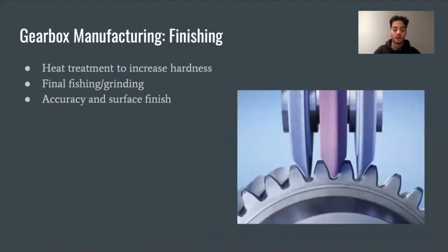After machining, gears usually require heat treatment in order to increase the hardness of the gear, and after heat treatment, gears usually require finishing to remove any distortions that occur during the machining or heat treatment process.